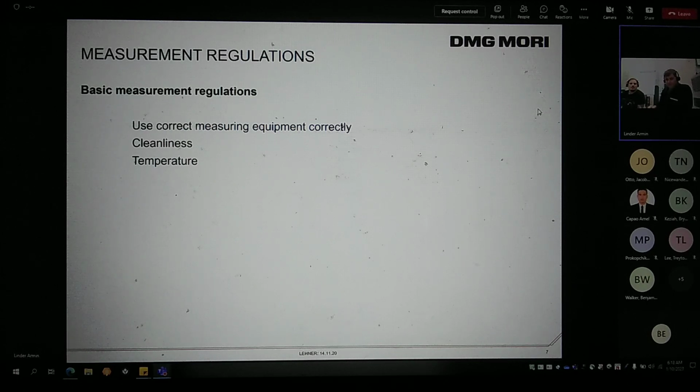I think most rooms here at the plant are now climate rooms, so we always have the same temperature. We call it a basic temperature value, which all machines have in the protocol. It will be measured at 21 degrees. One big thing to know.